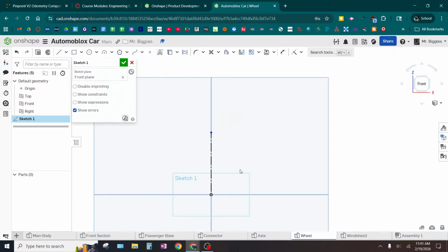Okay? And then I'm going to draw the profile of this wheel. So I need you to really watch carefully how I do my dimensions. But for starters, we're just going to do the shape. So this profile, okay, I have a vertical line that's basically the inside edge of the outer ring. Okay? I know that it's rounded on these inner edges. We'll use a fillet for that.